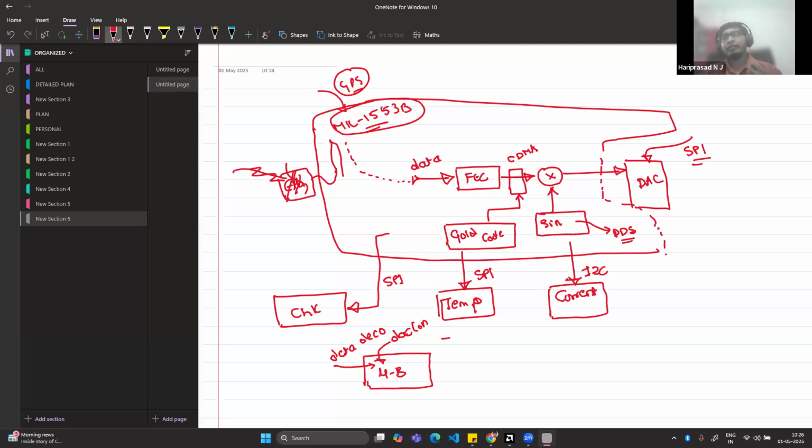No, right? Even if I read it every 1 second, I can put it into software, temperature sensor reading, and even the current sensor. Basically, these current sensors are for your system level error detection. Let's say internally due to temperature there are short circuits, or a sudden spike in the current happens. Immediately we have to go for shutdown mode. So all the peripheral access, like clock configurations,